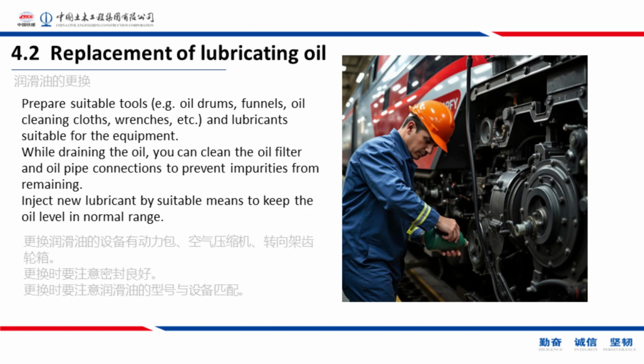PPT 40. 4.2 Replacement of lubricating oil. Prepare suitable tools, e.g. oil drums, funnels, oil cleaning cloths, wrenches, etc., and lubricants suitable for the equipment. While draining the oil, you can clean the oil filter and oil pipe connections to prevent impurities from remaining. Inject new lubricant by suitable means to keep the oil level in normal range.